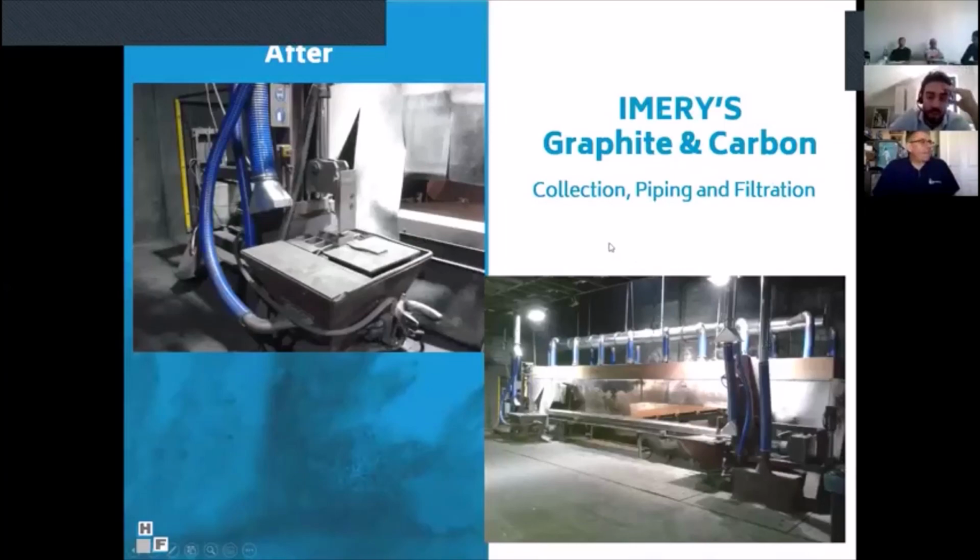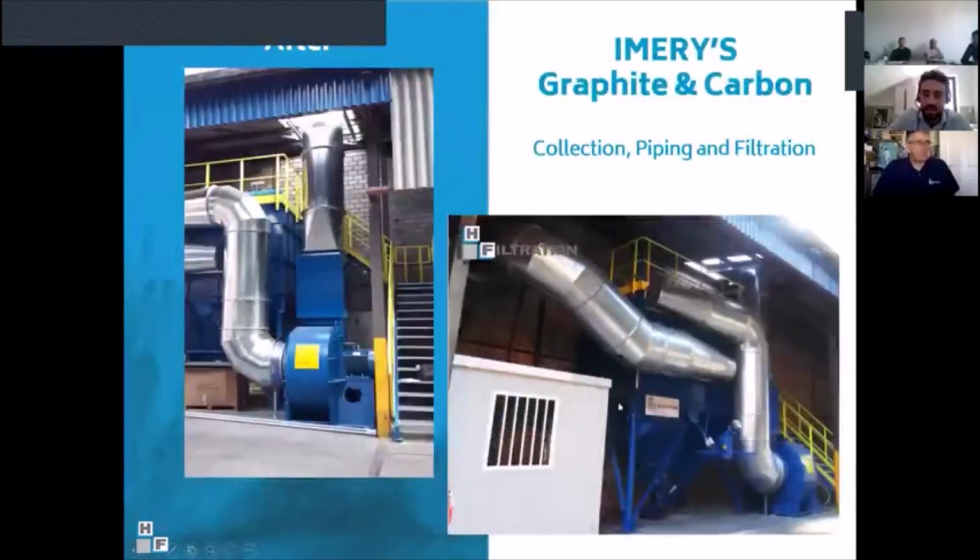We will see it in the video. This is the filter we chose. It is a cartridge filter, but made of high thickness carbon steel. We also chose a very big ID fan, 55 kilowatt installed, for more or less 5,000 cubic meters of airflow.